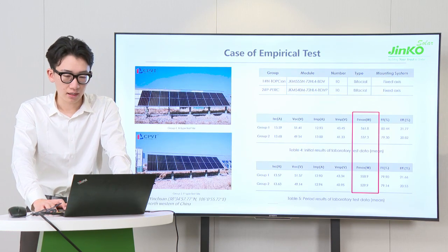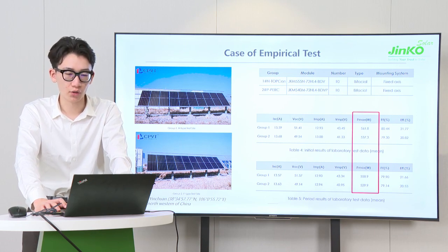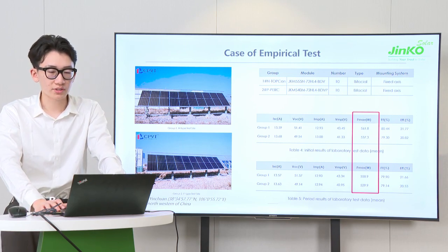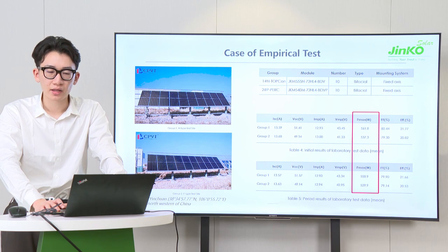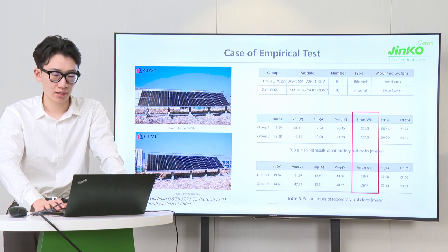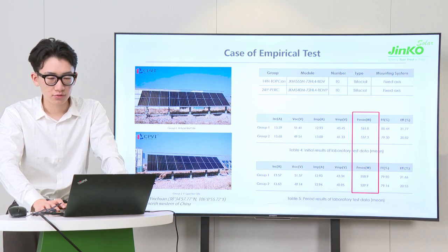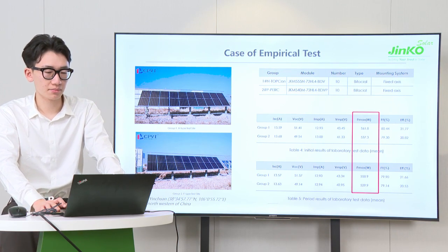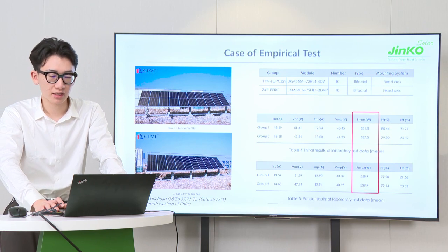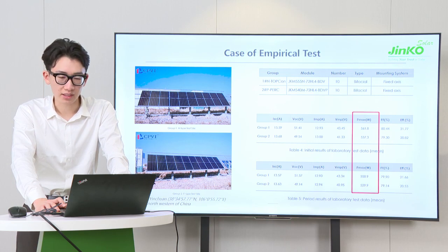As shown in the left picture, an output energy yield and performance stability comparison study performed on PERC and TOPCon N-type modules was conducted by CPVT. 2 groups of a total of 20 pieces of bifacial modules of 2 different technologies were selected from Jinko Solar. As shown in the red area of the tables, the average degradation of group 1, TOPCon with fixed axis, and group 2, PERC with fixed axis, is about 0.51% and 1.38% respectively. Light-induced degradation of N-type TOPCon is much less than PERC.